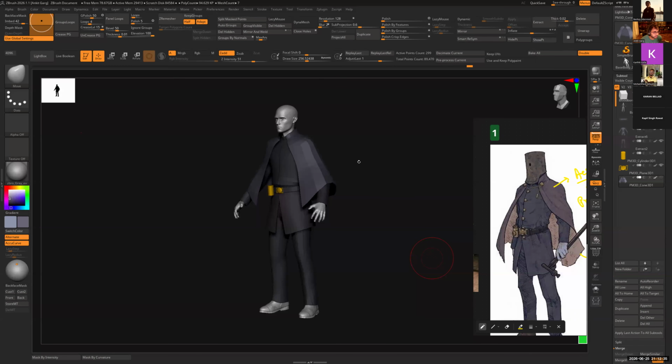How many UV sheets? Oh, sorry. Yeah, KZ asked a question, how many UV sheets you would use. It's a subjective question. Again, a lot of these are very subjective. Whatever answer I'm giving is not the absolute answer, but let's say a ballpark. Ayub, I'm going to mute you. Sorry. So let's say a logical answer for something like this would be you'll have one sheet for the upper body, one sheet for the lower body and the shoes, one sheet for all the accessories, and then maybe the cape is on a small fourth sheet. So 4 sheets, give and take. Fifth one might be there if you're able to see the body and the head.